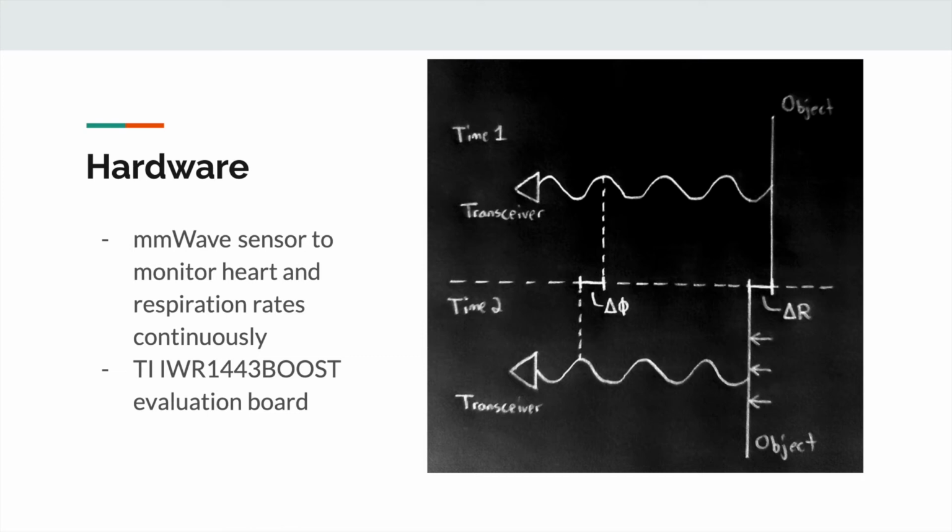Sample data is processed by firmware on the board, with a respiratory and heartbeat waveform being extracted through bandpass filtering. The firmware also processes the heartbeat waveform to obtain the time indices of the heartbeat peaks. This data is then passed in packets over a UART connection to software in order to calculate the heart rate variability metrics and to display breathing and heart rate data.